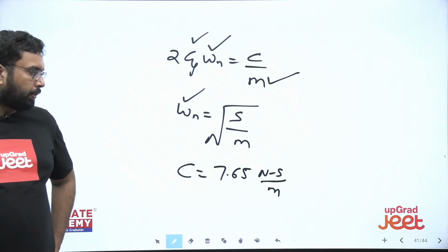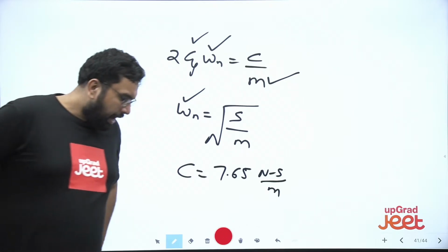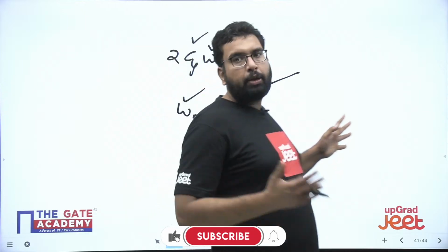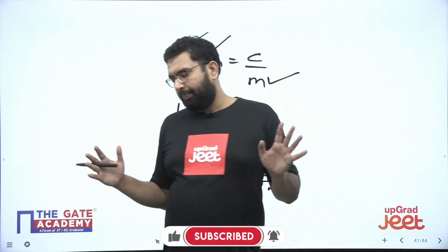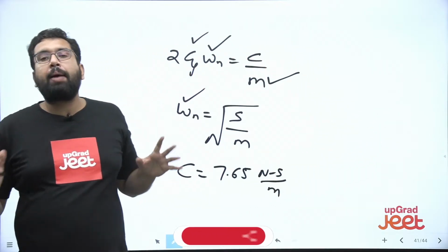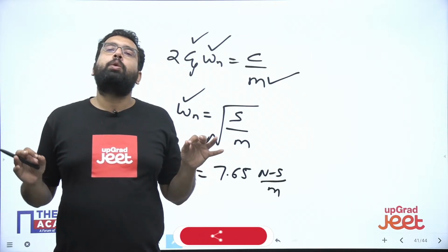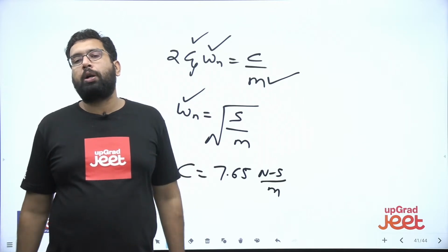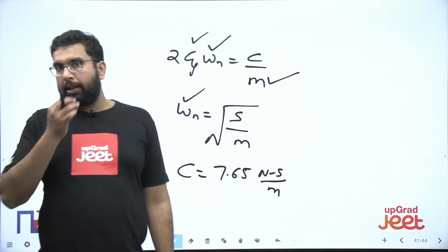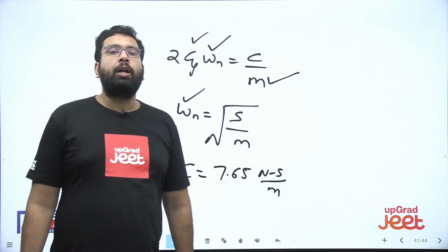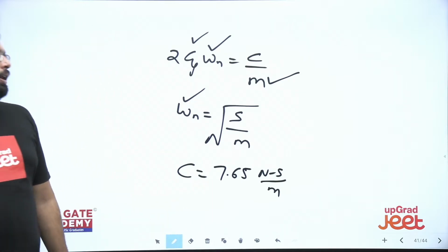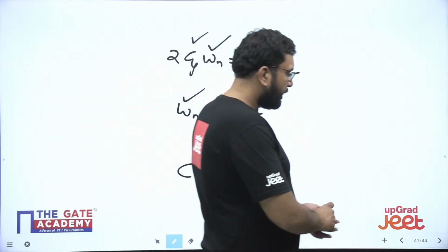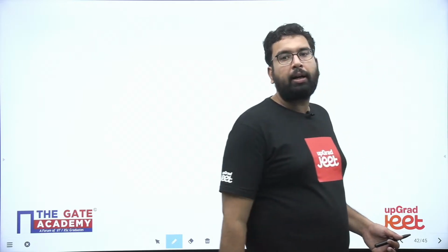Okay. Now one last type: in this we can apply the torque method also in the same way. But when we have the damper, always remember to take the force proportional to the velocity, that is x dot. You will have to make the equation like the standard generalized equation, and then you can compare.